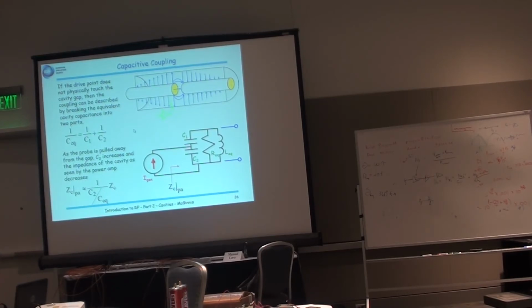And in general, what they do is they do this with HFSS or something like this to really tune these things out. They'll put all sorts of doorknobs on that. One of the things that you'll see, maybe, I'm not sure if we have some of these in here, I'm not sure if Ralph brought some of the old stochastic cooling boards, probably not, is that you'll see these things have these very complicated shapes. And you guys, how did you guys do that? You're geniuses. Well, what we did is we put a simple shape down, and then we took an X-Acto knife, and we looked at things like time domain reflectometers, or we looked at instruments, and we just kind of hacked and carved until we got what we wanted. It was kind of like craftsmen of the old world way of doing things.